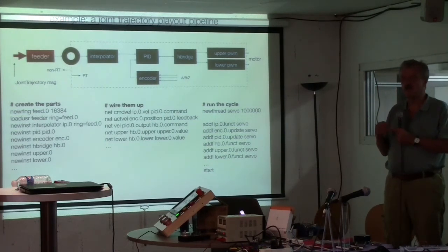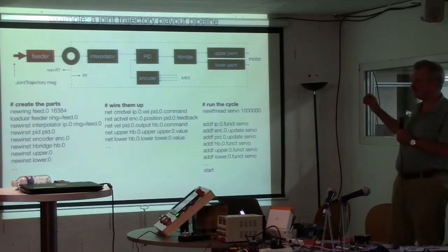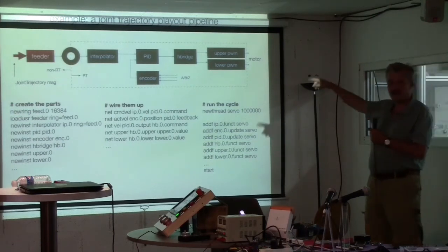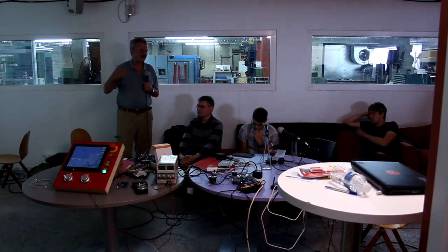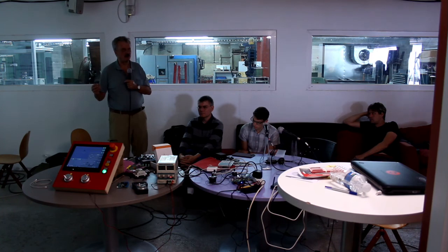Typically, you need to do this for new hardware, because where the whole thing interacts with the hardware, that is very platform specific. So some of these HAL components are called HAL drivers, and they actually interact with the hardware. Bringing the whole thing to a new platform typically involves new hardware drivers, new GPIO numbering, that kind of thing.